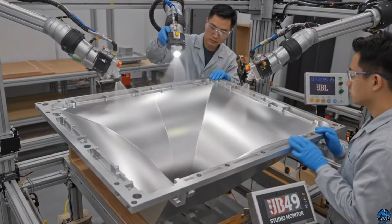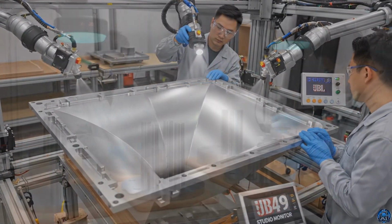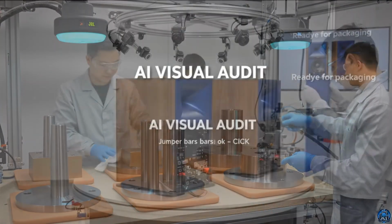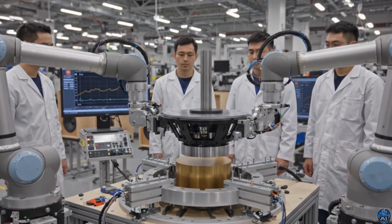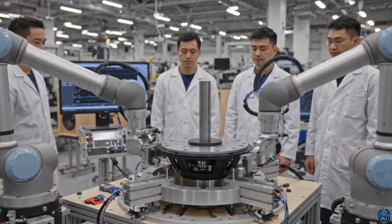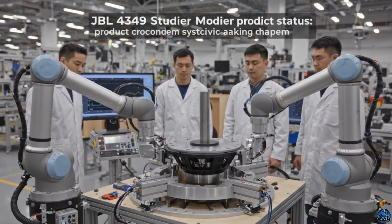AI guidance is active. Ensure all adhesive fragments are removed. Ionized air cleaning is underway. Magnets and pole pieces are pristine. Displacement sensors look good, 1.3 microns. Gap is uniform across the circumference. Torque set, proceeding with tighten.